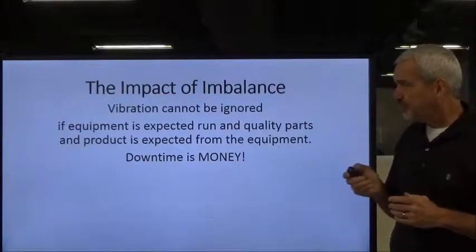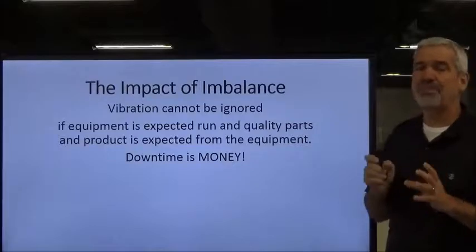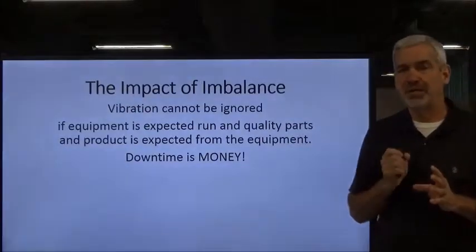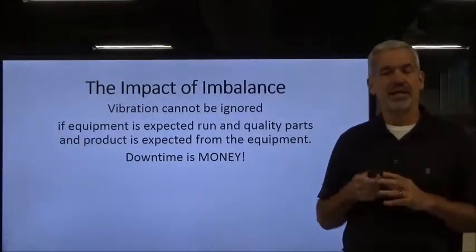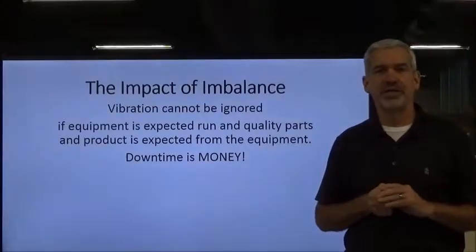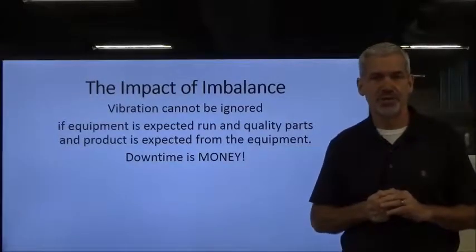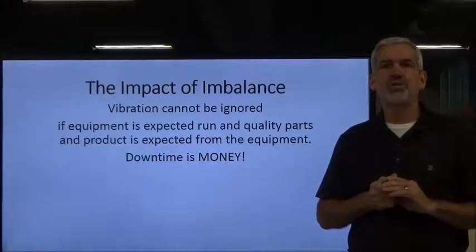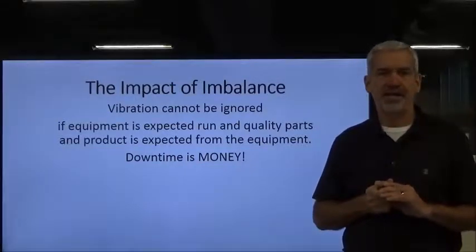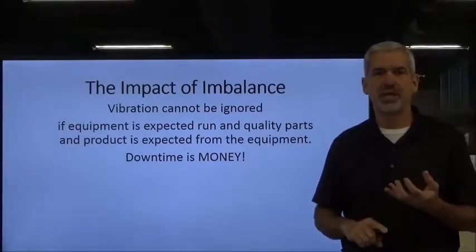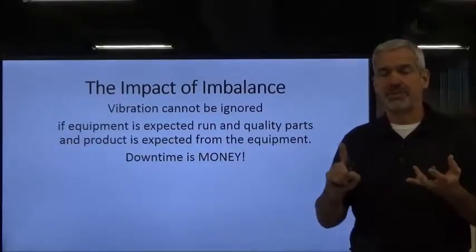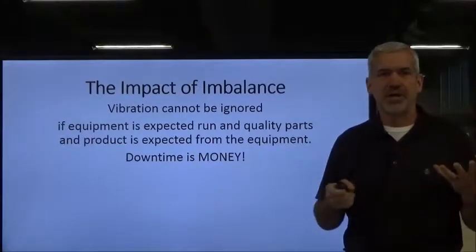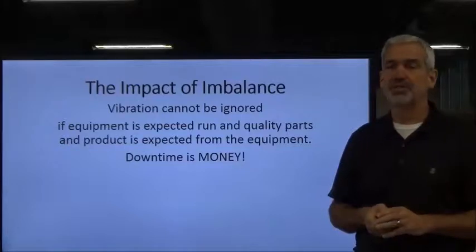So anyway, vibration cannot be ignored. I promise you, if you ignore the vibration, it will come back and bite you. If you ignore that vibration in the wheel or tire of your car, I guarantee you, your front end is going to wear out a whole lot faster. You've got ball joints, tie rods, or excuse me, rod ends, and other steering and suspension components that are going to suffer as well.